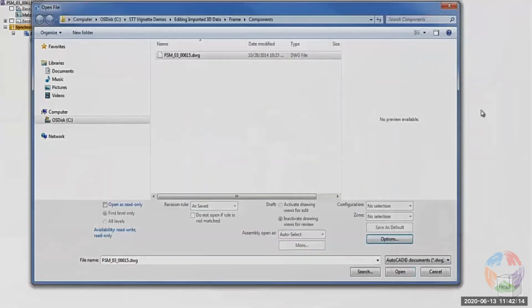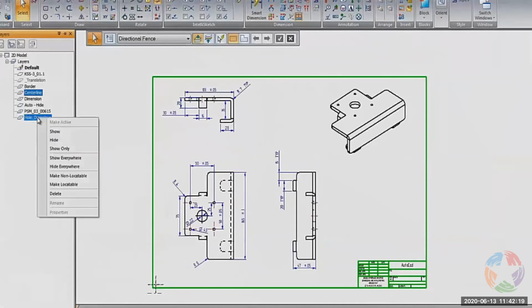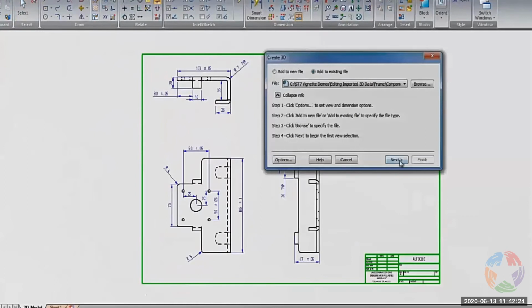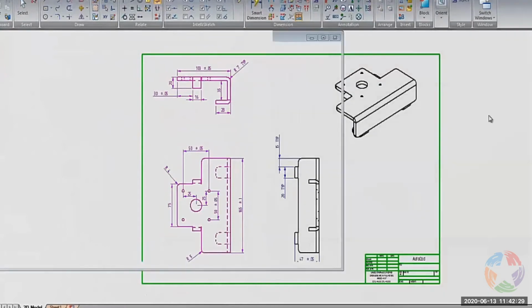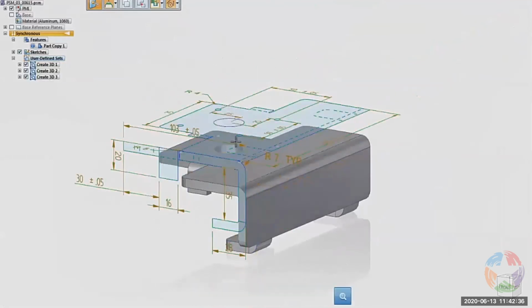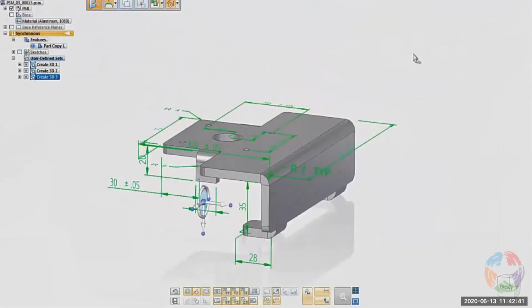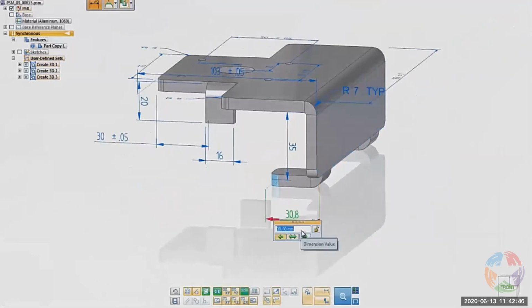And in this case, for those of us who are advanced, you may have a 3D model and a 2D drawing of that. Well, it'd be great if you could marry the two together, meaning how can I bring information from a 2D drawing over and lay it on top of my 3D model? Companies do this all the time because they need accuracy. And so here we're placing that 2D information on top of the 3D, but now the dimensions are attached to the 3D and you're able to make those changes.